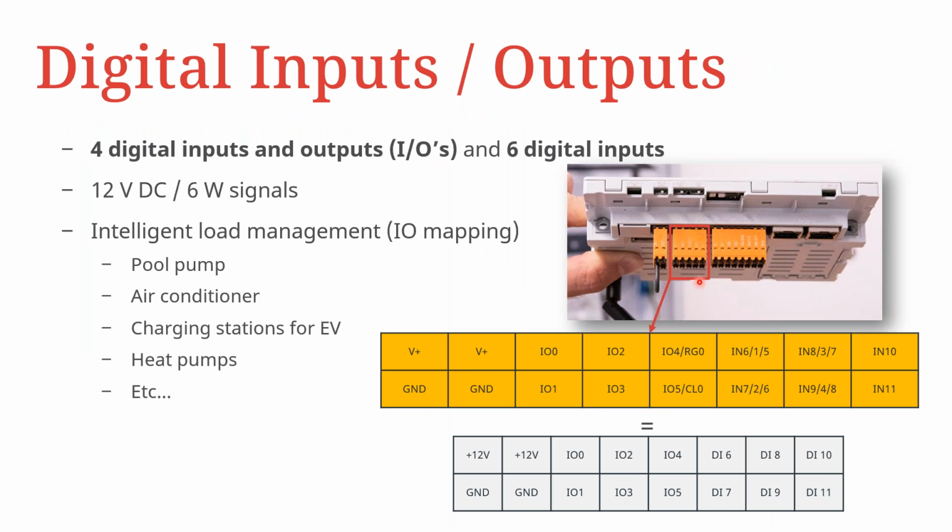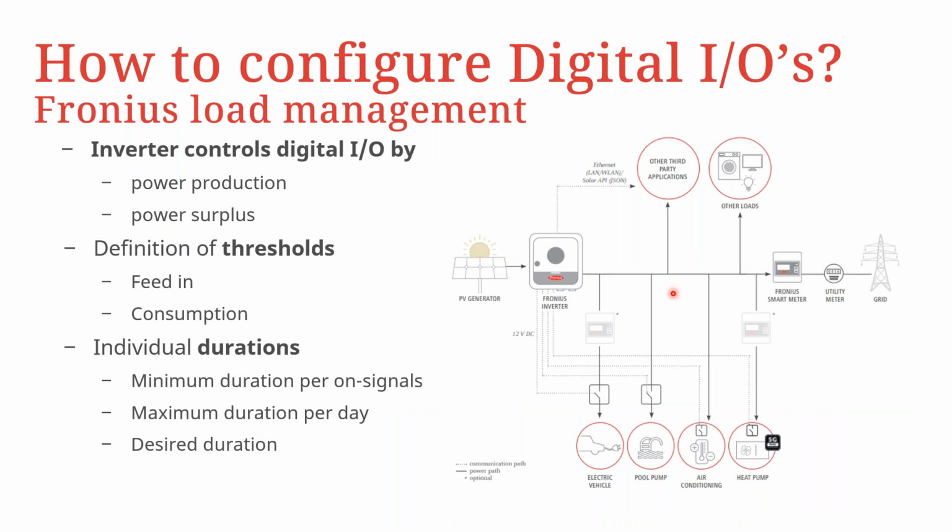So what is done is that, of course, you have a wire-to-point connection. These cables come to the external relay, as mentioned. They activate the coils of these external relays, and then the contacts of these external relays activate or power these devices or appliances, as you can see in this case. I'm just giving a summary of how this can be achieved.